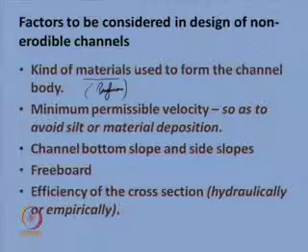of the channel, right. You are quite aware now, because different materials have different roughness coefficients, and once the roughness coefficient changes, the flow or the discharge changes quite immensely. So, it is one of the most important aspects while designing the non-erodible channels. You also need to consider the minimum permissible velocity.